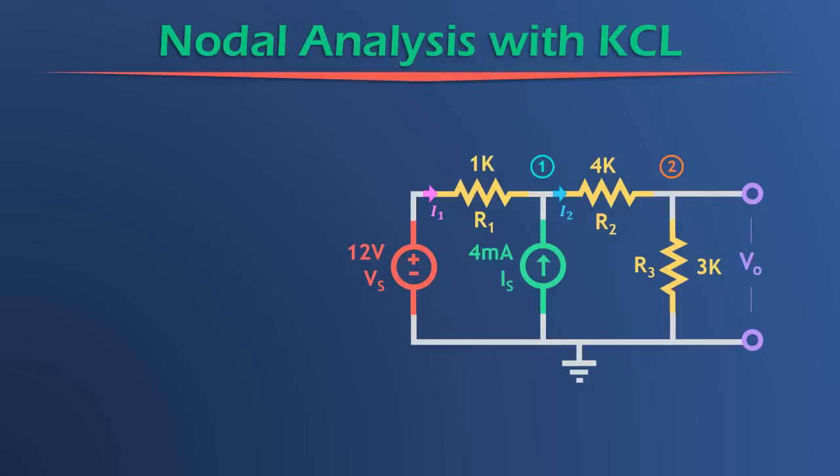method. Again, let's start with a KCL at node 1. So the KCL at node 1 is going to be the same: I1 minus I2 plus IS, and you should know why we have negatives and positives there. And as we start expanding it out into the nodal analysis form, the beginning starts off the same. Vs minus V1 over R1, which corresponds to the current I1 here. But now I2 we define as V1 over R2 plus R3.